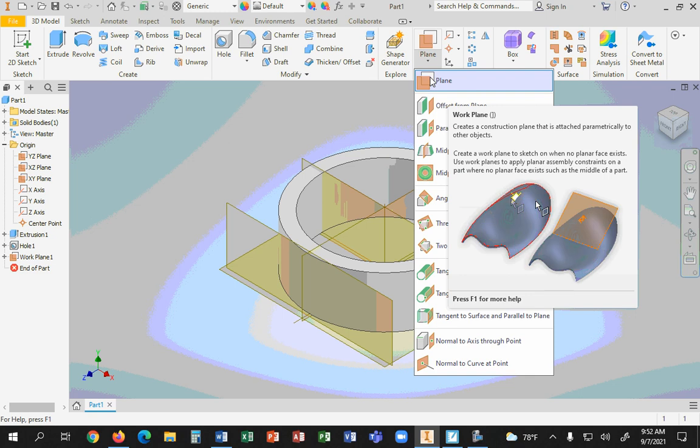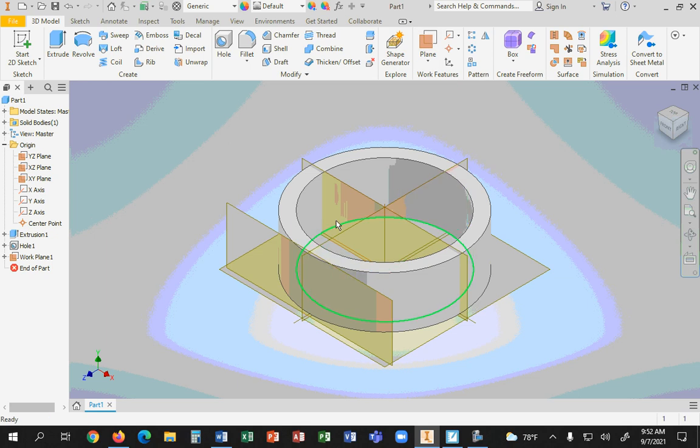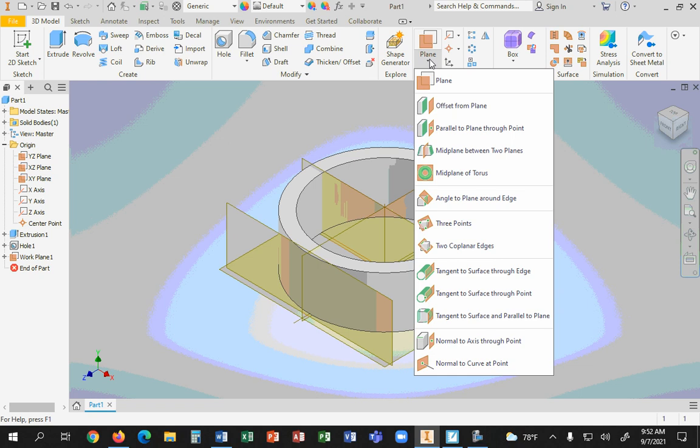So that later on, you can just pick plane, pick this existing plane, pick the face of the object, and there it is. Now, if that's the wrong plane, the wrong spot that you want this on, that's a different conversation. I'll show you how to create a plane in a specific position later for a different project.